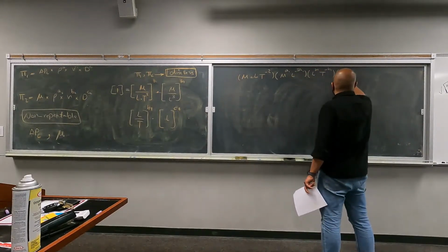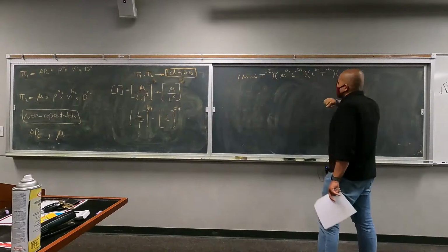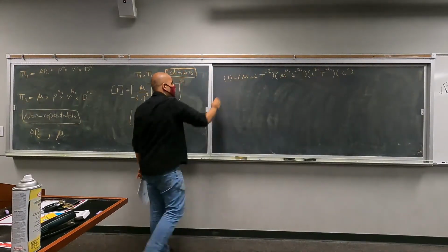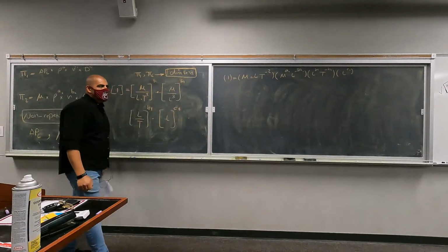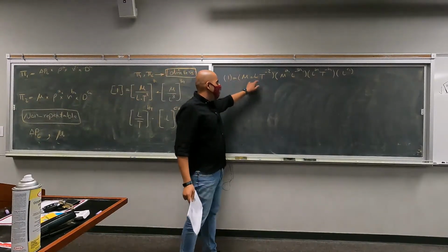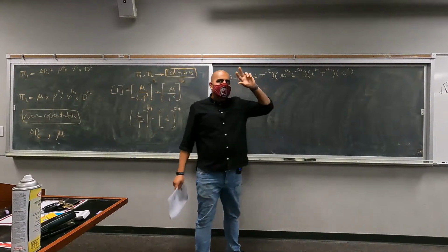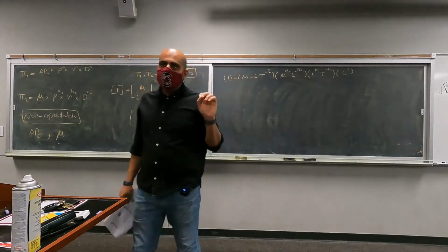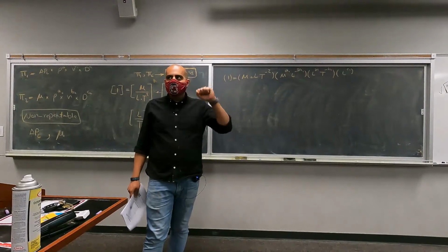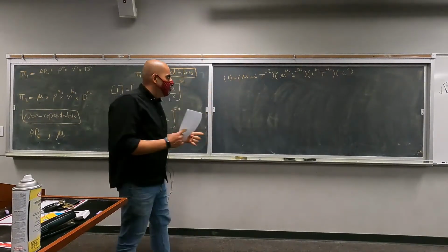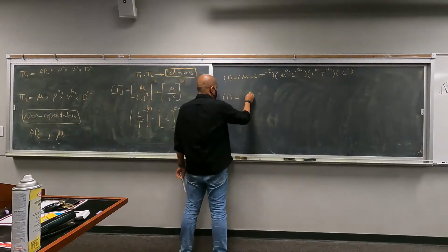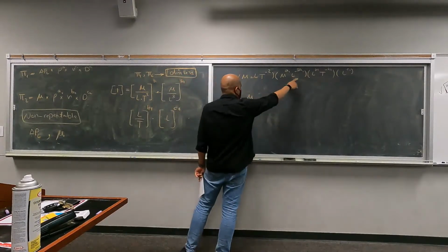And L to the power c1. All of these have to be equal to 1. What does this mean? This essentially means that all of these primary dimensions, all of their powers have to be 0, right? Whatever to the power 0 is going to be equal to 1. So we have to rearrange this to get the powers for all of these individual things.